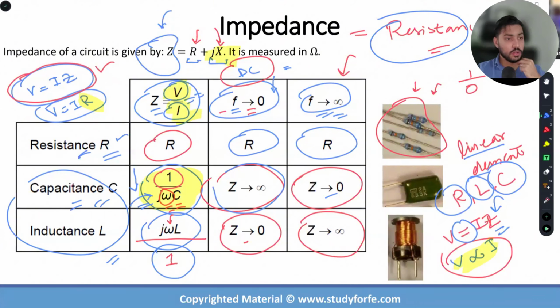Another follow-up question. Can you tell me some examples? Give me some examples of non-linear elements. Well, they are the ones that don't hold Ohm's law, for which the Ohm's law does not apply. Okay. Give me some circuit elements. Give me some specific cases. Sure. Your PN junction diode, right? Because the PN junction diode does something like this, correct? In terms of the voltage current relationship. What else? Your transistors. The relationship between voltage and current is not linear in all the three modes of operation. You're talking about BJTs, then you have cutoff, you have linear region, you have amplification. Same thing for MOSFET, right?